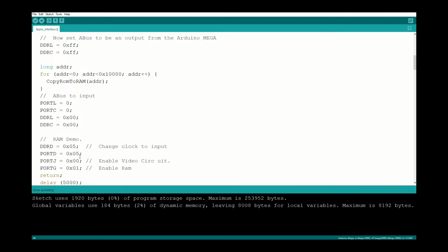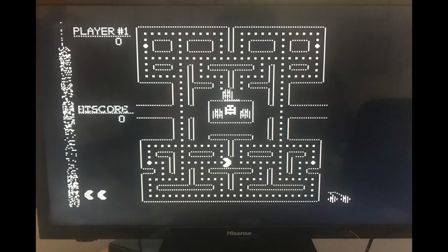I need to inspect the memory before I start the CPU, and I'm going to do that by keeping bus enable low. This will deny the CPU any access to the memory. So now I'm looking at the image in RAM before the CPU's had any access to it, and it looks good. So I think the CPU itself is corrupting the data in the memory.